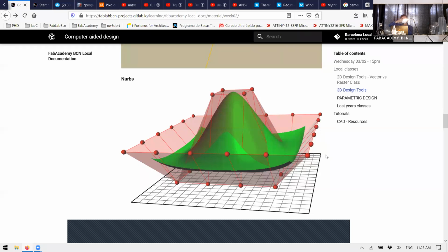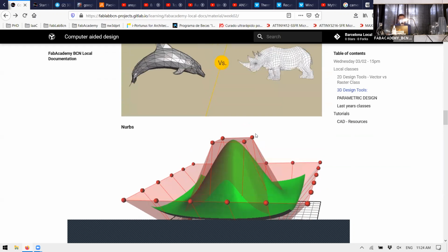And now that we have three-dimensional curves in the space, we will create the average one again between all of them. That average in X, Y, and Z will actually create this NURBS surface. What happened? NURBS in general are way easier to manipulate because they have control points of edition. And also they are easier to modify in general than a mesh.